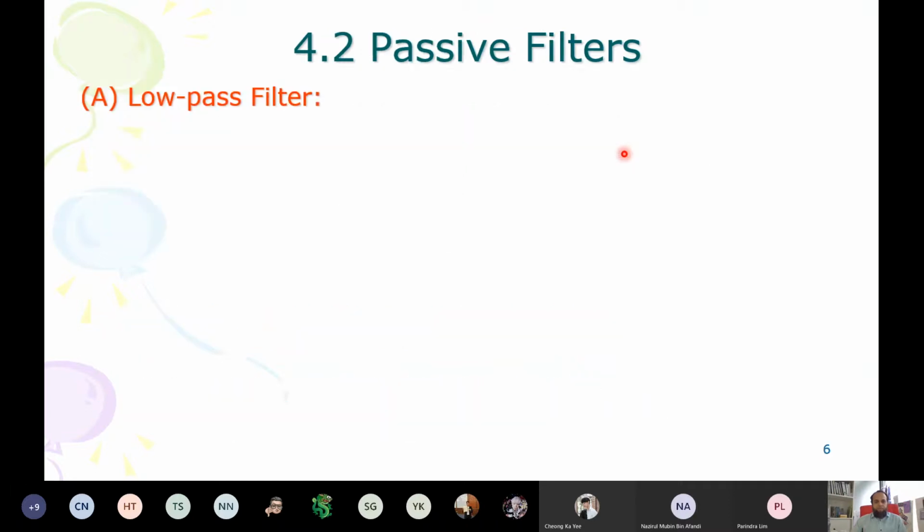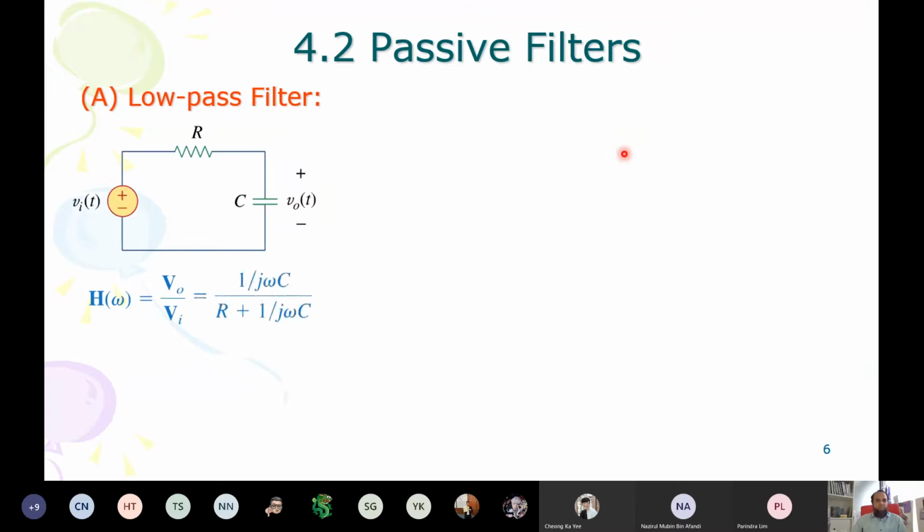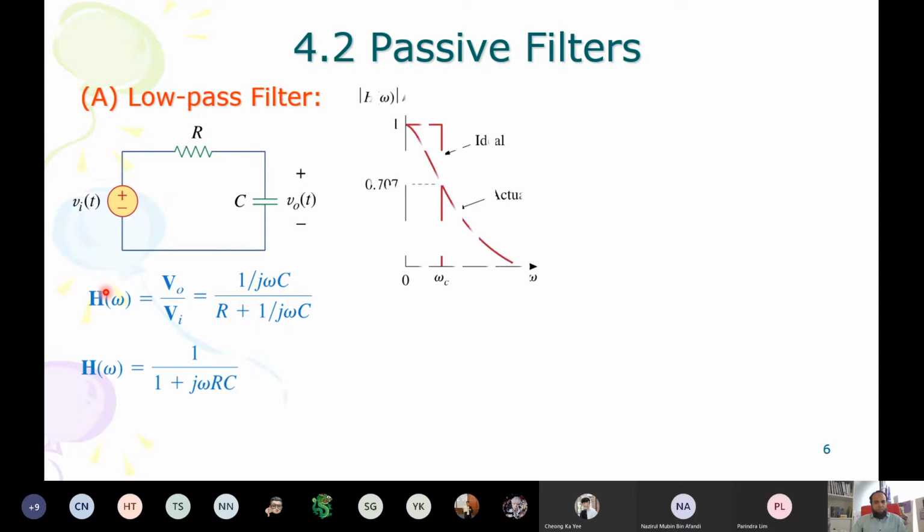Okay, so I think we did a lot. So the main idea is to find the transfer function. Once we have the transfer function in standard form, put omega 0, omega infinity, see what is the output. So you can see that if omega equal to 0, we get 1. For omega infinity, we get 0. This shows that this is a low pass filter.